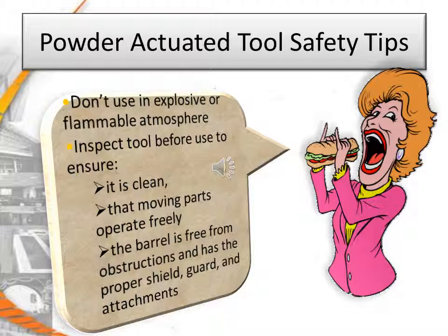Powder actuated tool safety. Never use them in explosive or flammable atmospheres. Inspect the tool before using to ensure that it is clean, its moving parts are operating freely, the barrel is free from obstruction, and it has a proper shield, guard, and attachments.